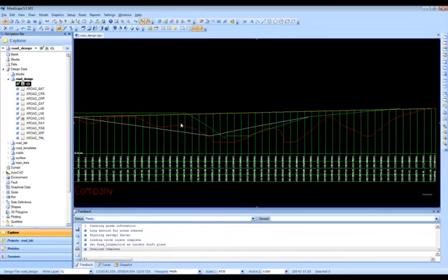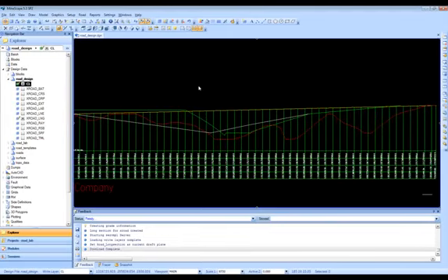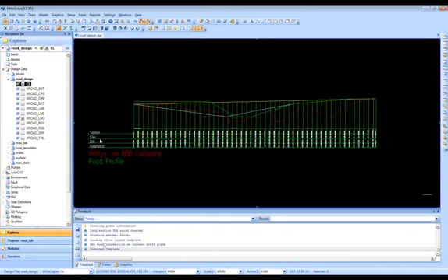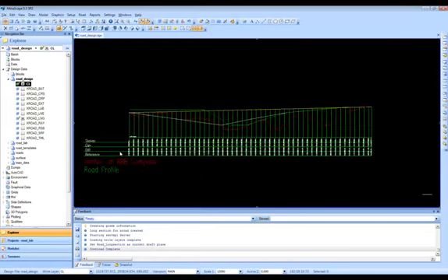This red line is the topography that I'm going across, and these other lines are just various lines that I have in my current design file. They really don't reflect anything. The information along the side is what I asked for in my road profile setup. So I've got some numbers here along each of the stations. They represent what the station is, elevation difference, and reference surface.